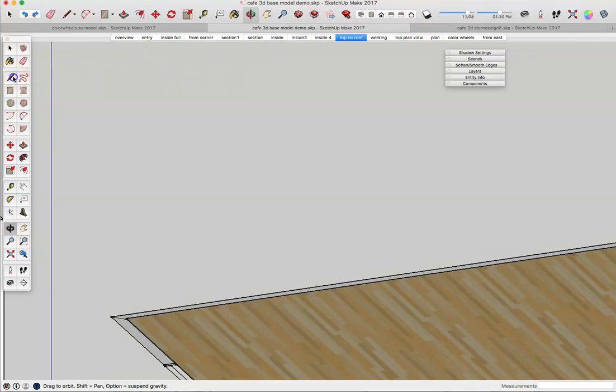Okay, and so what I want to do is this wall over here comes off the existing party wall. Should also be 18 inches, but let me make sure with my scale. Nope, it's actually 2 feet. Good enough. So I'm going to come in here. I'm coming up, type 24. It's easier when you can just type the inches and not the foot symbol.